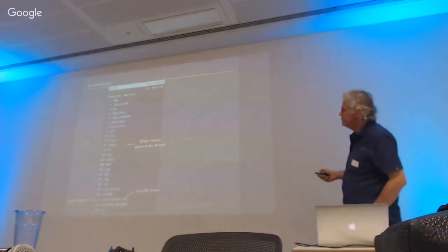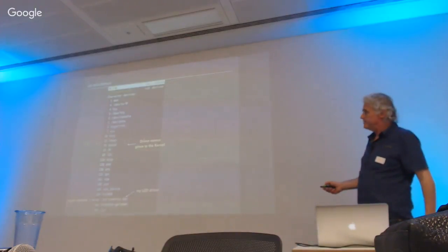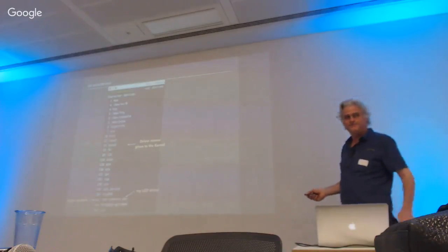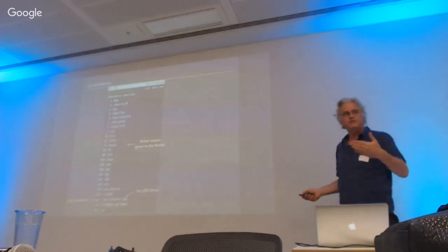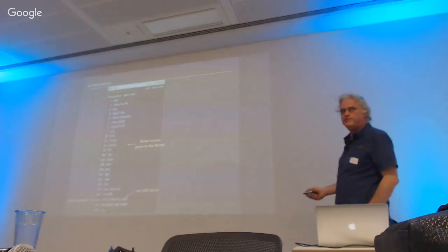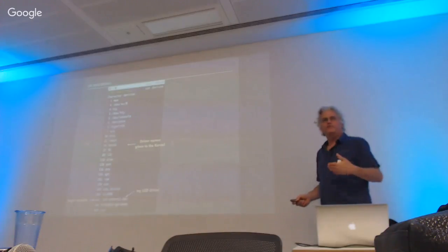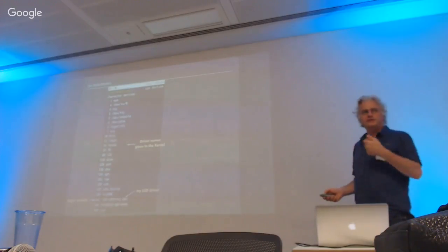These are all character devices. For example, these TTY consoles here are character devices. That's a virtual console. That's a character device. The I2C driver you were dealing with, it's also got a character device driver controlling it. All the information is coming in a sort of byte stream, basically. The SPI bus here has got a character device driver. In this case, on the Raspberry Pi, the driver's got major number 153. And again, the SPI bus is basically a byte stream orientated bus, so it would have a character device driver.